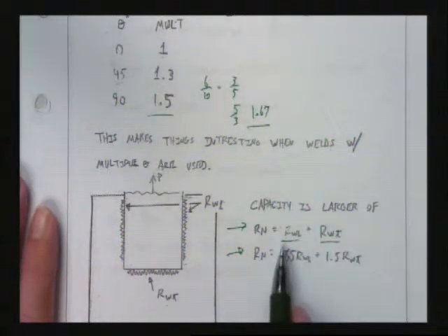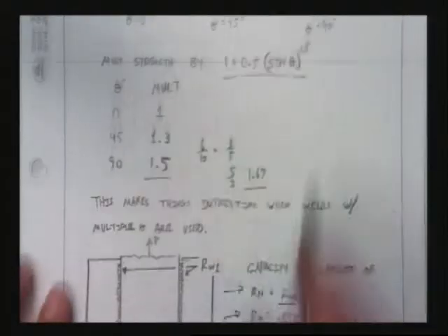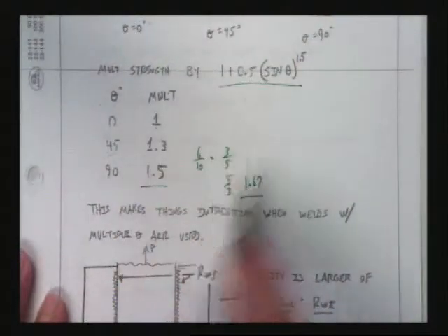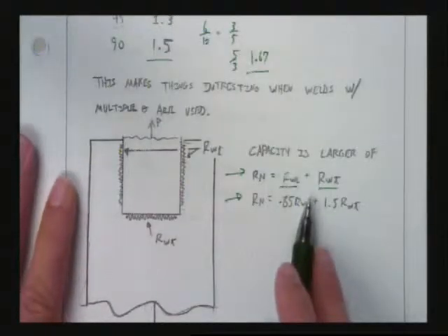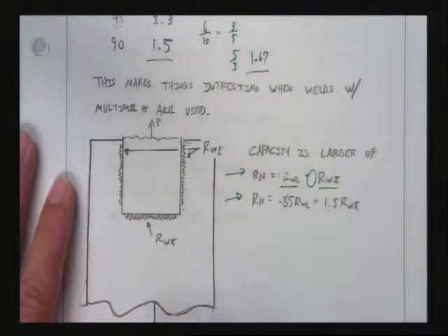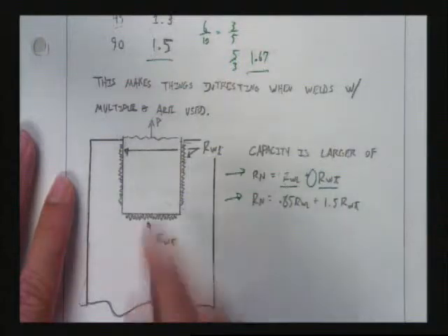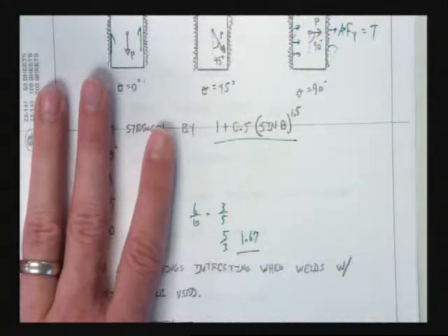The reason they allow this equation doesn't quite make sense. Here we're all spending all this time and energy trying to figure out what the welds are in shear and tension, and then we come down to the end and we just say, act like there's no modification factor. Act like this equation is 1 at the top. That's what they're saying here.